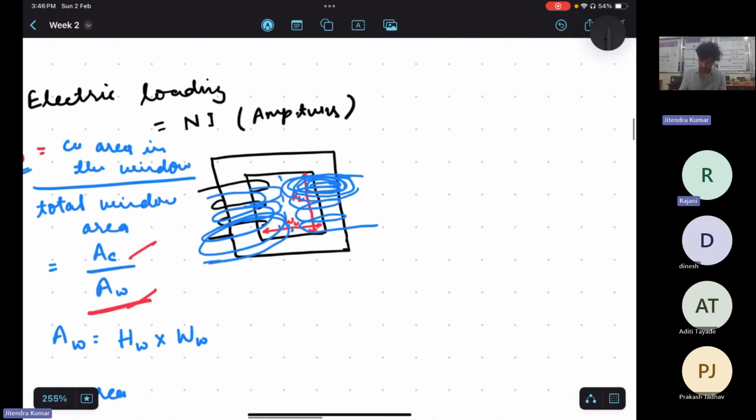Let us suppose that with this winding fashion, you will have a flux flowing in this fashion. Now, if you have flux flowing, then you will have a circulating current. You keep your thumb in the direction of flux and you rotate your fingers. The direction of curl of your fingers will give you the direction of circulating current, which is known as which current? Eddy current, exactly.